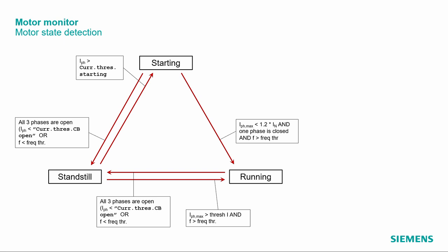And we can also go the other way around. This is a little bit a special case. On the one hand, if the motor is running and you switch on the relay, and the relay sees that there is a current flowing, then it will go from standstill mode to running mode after a certain time. So it checks first the situation and then switches over to the running mode. And we have this path also for dynamic effects.